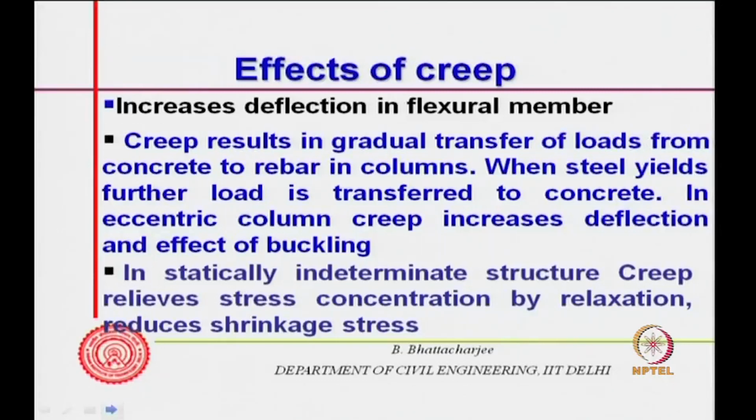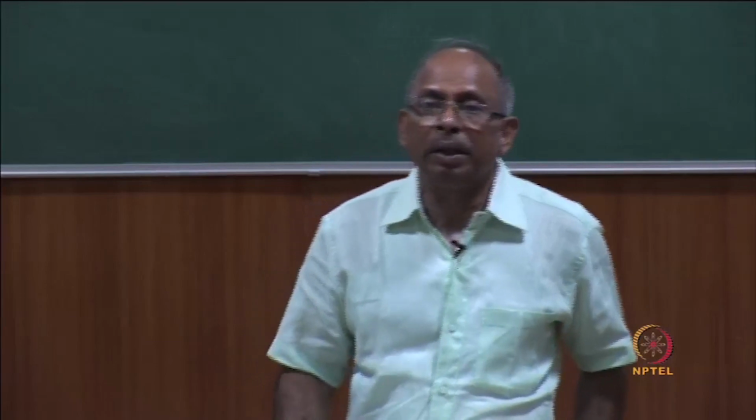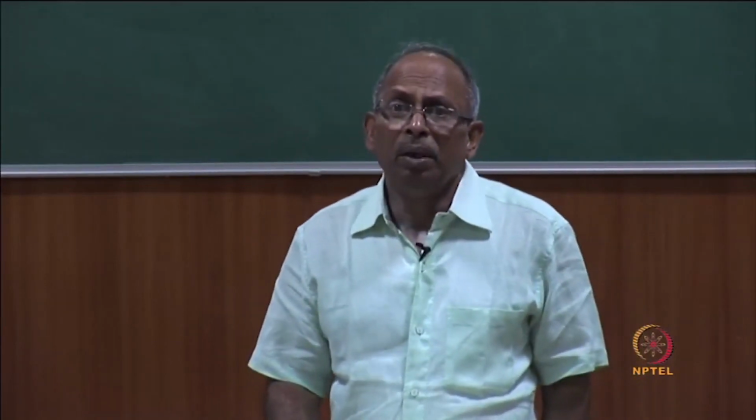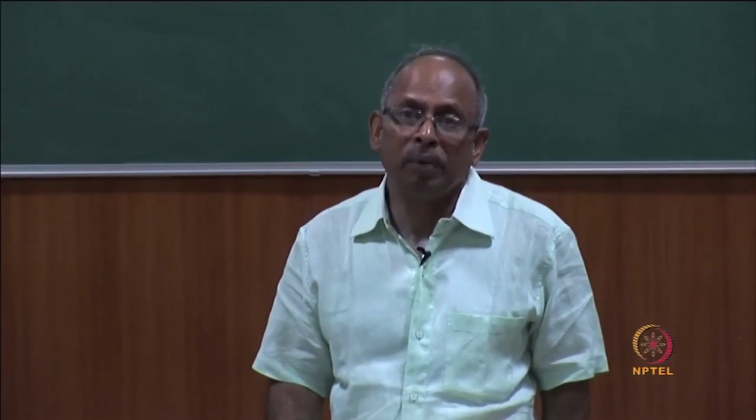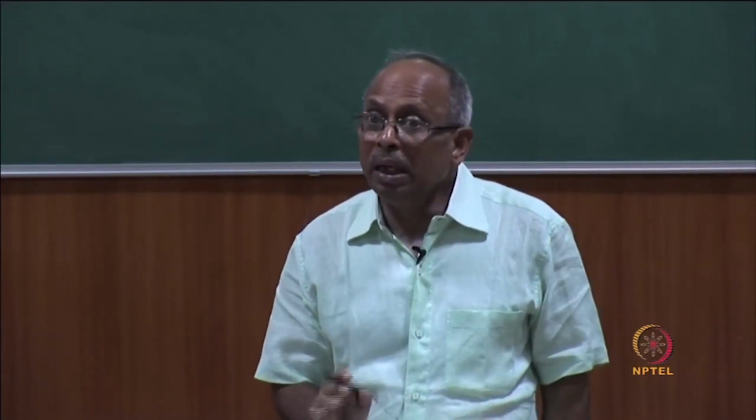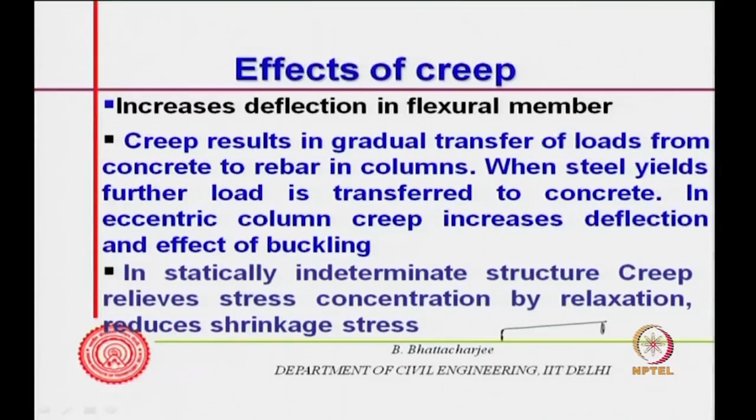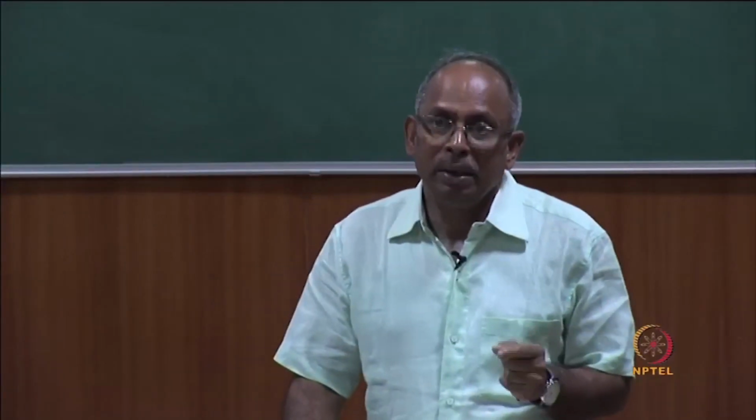In statically indeterminate structures, creep relieves stress concentration by relaxation and reduces shrinkage stress. Now, what is an indeterminate structure? You have additional restraint. For example, in a determinate structure, you will possibly have a roller and a hinge here. So, this can move, but if you make another hinge, two hinges here, it becomes indeterminate. So, therefore, it is restrained. Statically indeterminate structures are restrained.